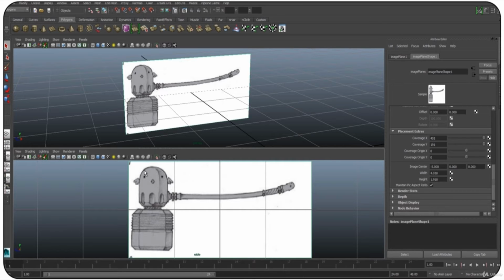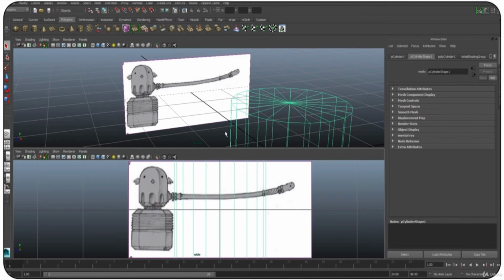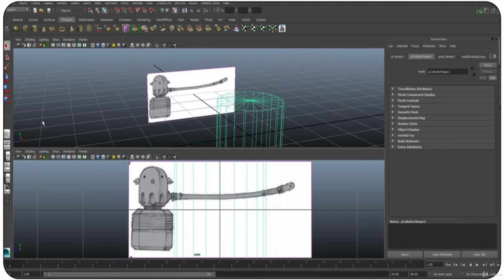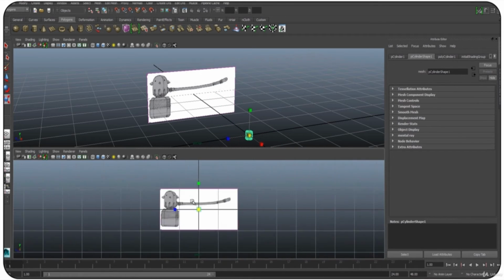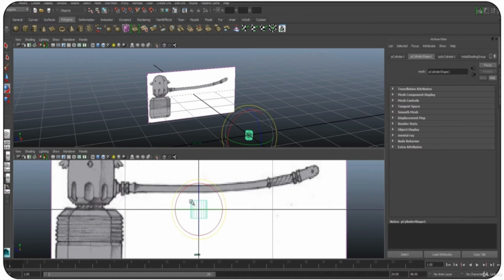And this looks like a small cylinder. So you can use a cylinder for this, and you can create the same thing with the help of a cylinder. One by one I'm going to use these to achieve this hammer model in the Maya software. First of all I'm going to use a cylinder here. This is a cylinder and I'm going to resize it. You can use F to focus the model, E for rotation, and J for rotation snap.